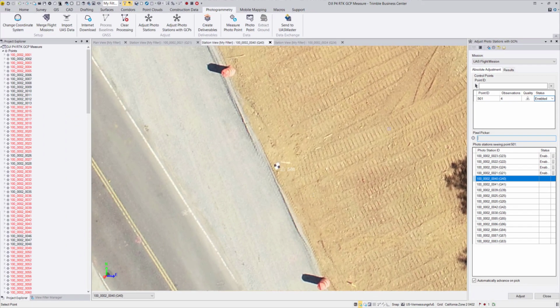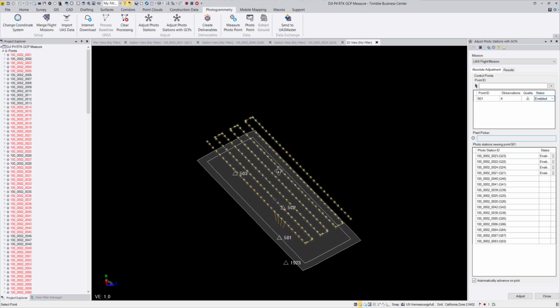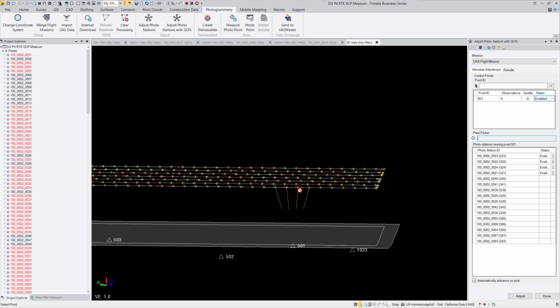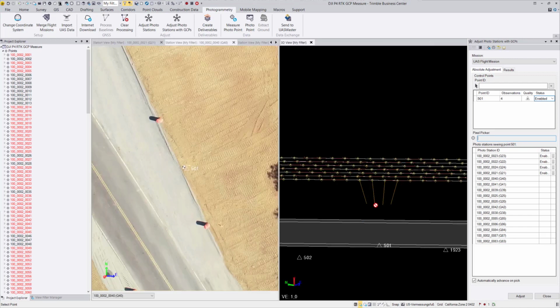In TBC, you can also have multiple views on different screens. So I can open the 3D view, and in the 3D view I can rotate this whole part by keeping the left mouse button pressed, and you see these orange lines. Perhaps I can right click my tab and say I want to show this in a new vertical tab. So this view is now on my right side, and on the left side I can still continue to do my measurements.